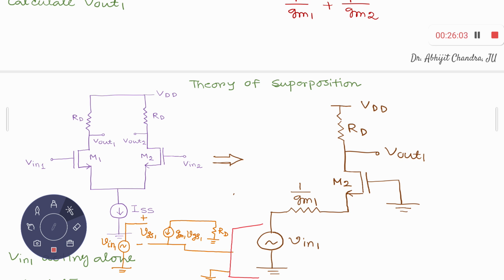Remember, whenever we are performing this Thevenin analysis, first of all, for calculating this Thevenin voltage, you have to ensure that this part of the circuit, for which I am interested in finding out the Thevenin equivalent model, is disconnected from the rest of the circuit. And I would like to find out what is my open circuit voltage over here between these two terminals.